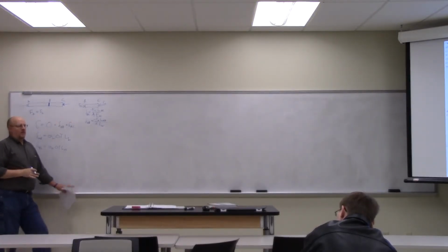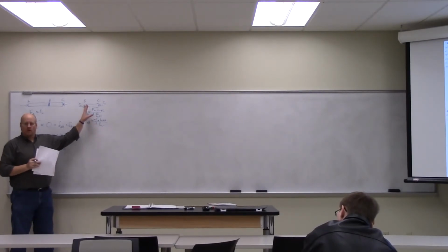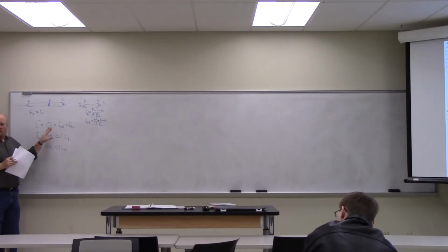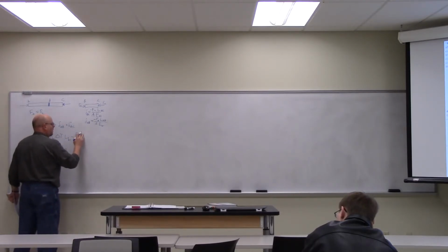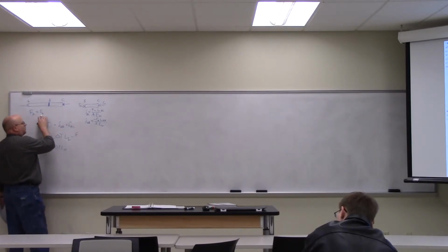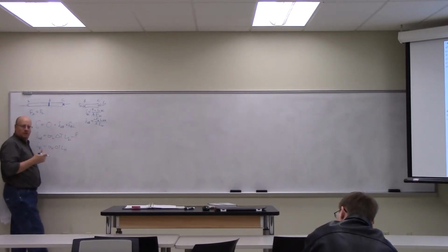Right, so now we have a mechanical displacement, elongation, and a thermal elongation. And the total elongation of each piece is the sum of those two, superposition. So the total for AB is this minus F, well, since we have FA equals FC, I'm just going to call it F. Right?